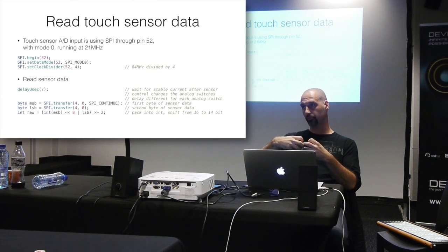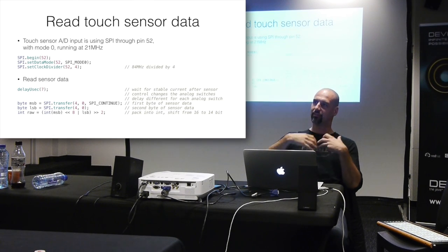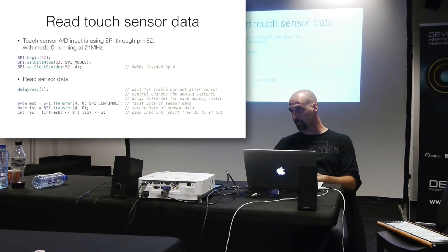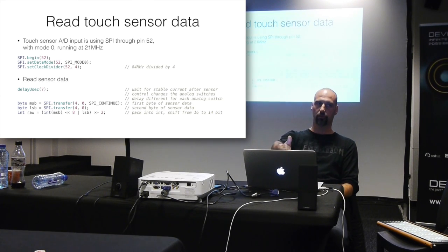You maybe only want it to pull slower, so that it sends less current, so that you can get less crosstalk, because your circuitry might be designed for lower speeds. Mm-hmm. And that's why you set this clock divider, so that your actual interaction with the peripheral interface is going to be slower than the maximum speed of the CPU.